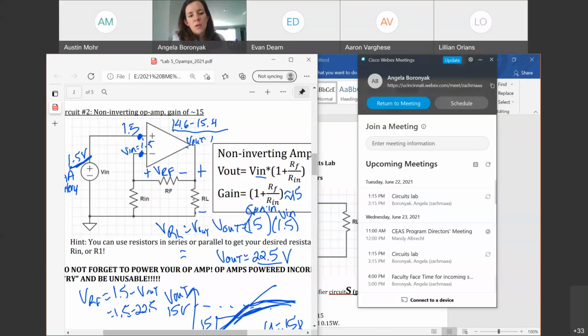Vn even at this point will have trouble, because while the voltage drop over Rn thinks it should just be from Vn to ground, really this current had to come from here and then go through here, because it couldn't go up here. If this current is off because V out isn't what you think, then this current is off as well. So it doesn't make the same voltage drop here either. All of your measured voltage drops for each of these three resistors in the circuit will be off, as in you will have a high percentage error. That's okay. In this case, that's why.